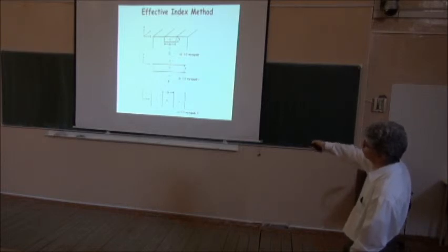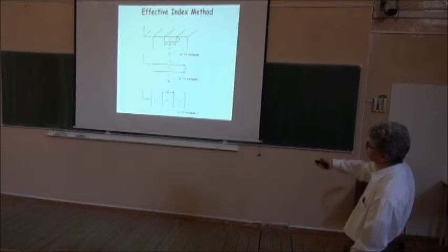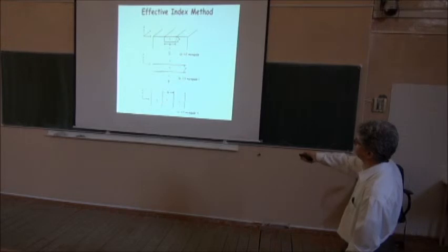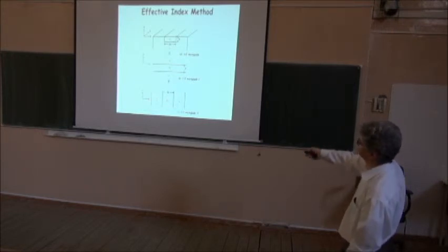I'm going to solve for the effective index of this structure. Once I find the effective index, I'm going to insert that effective index in this configuration and bring back the boundaries that I had before, now a width W, confining an effective index n sub I, surrounded by the refractive index here. I'm adopting the fact that N4 and N5 are equal, and I'm setting that equal to the refractive index of the substrate.